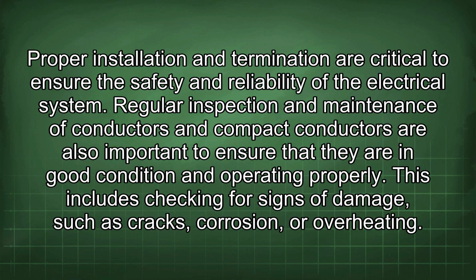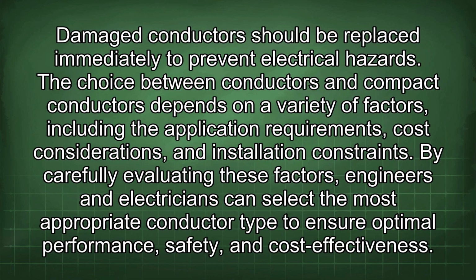Regular inspection and maintenance of conductors and compact conductors are also important to ensure that they are in good condition and operating properly. This includes checking for signs of damage, such as cracks, corrosion, or overheating. Damaged conductors should be replaced immediately to prevent electrical hazards.